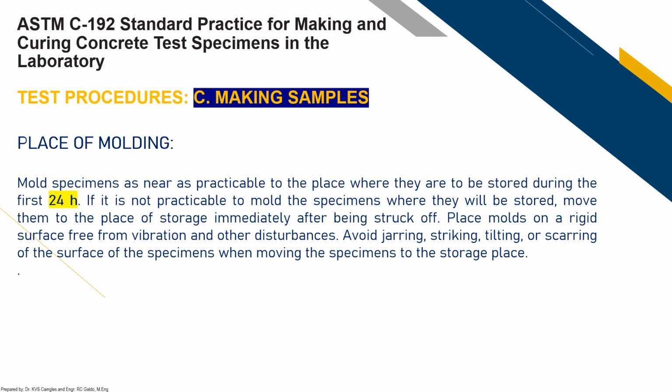Place molds on a rigid surface free from vibration and other disturbances. Avoid jarring, striking, tilting, or scarring the surface of the specimens when moving the specimens to the storage place.